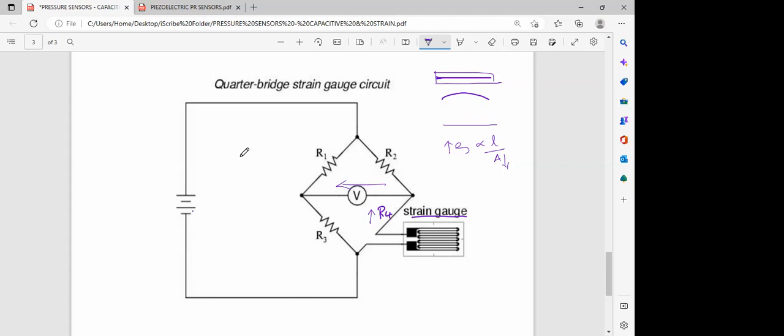Okay, the VDR was already installed. So when they recovered that, they came to know, because the strain gauge input is also fed into the VDR, that the strain gauge was giving a lot of alarms and that the master did not slow down the vessel adequately.